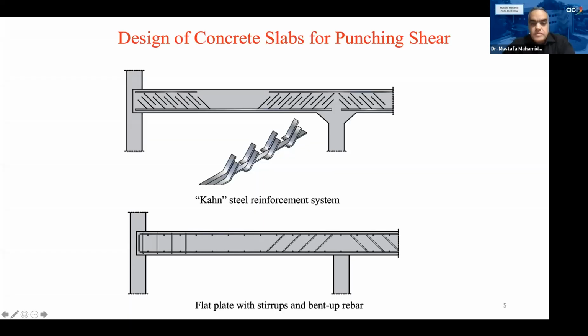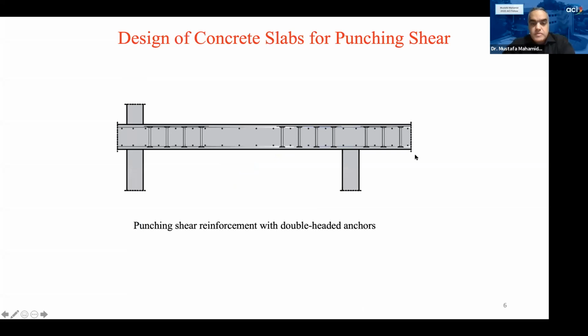We have the slab reinforcement, and then the bottom reinforcement would be bent to become top reinforcement, like they used to do before. We don't use this methodology anymore today for flexural reinforcement, and then use that diagonal reinforcement here for shear reinforcement for punching shear. And then later on, the development led to the use of headed studs, single or double-headed studs, as shear reinforcement for punching shear. So that was the other solution that was used later on.